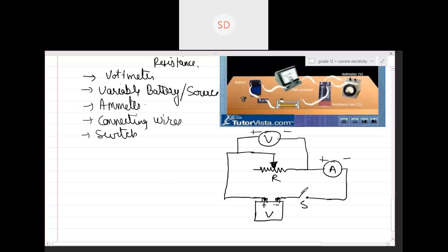Can you see over here what will you do? You will first fix the value of resistance. You'll move this. Can you see where I'm pointing? This thing on the rheostat can move, slide up and down on this rod. So basically, if you place it over here, what will happen? Current will come from here and only take this much length. So can you say this much length is excluded? Is this clear, guys?